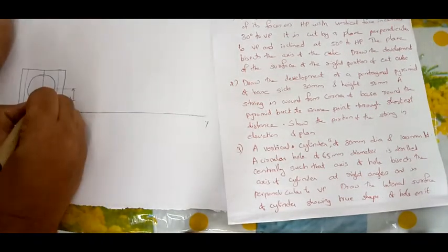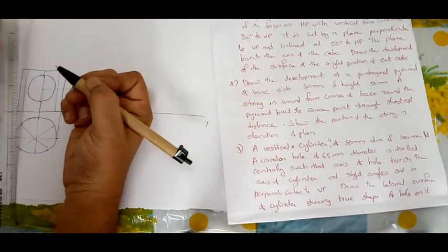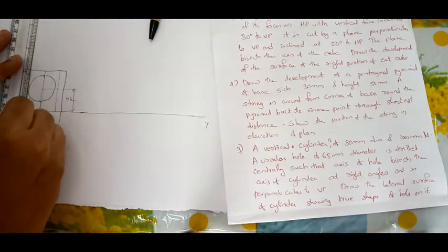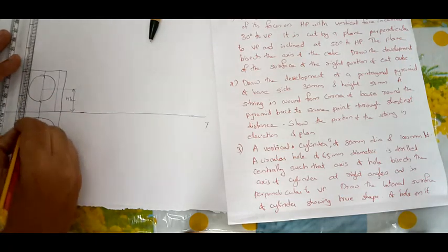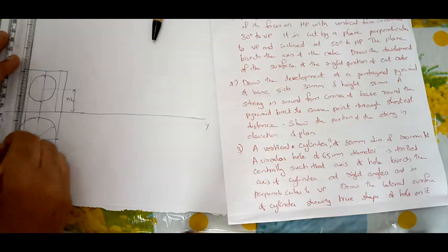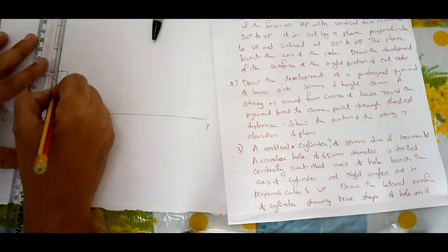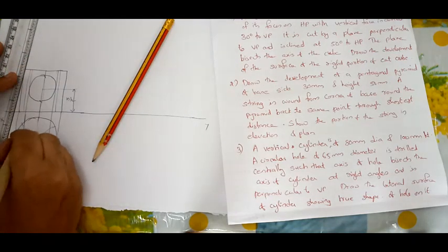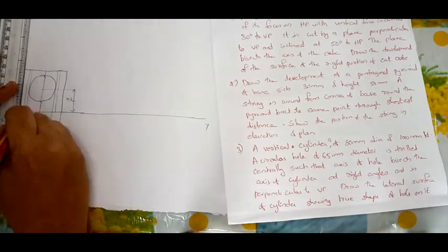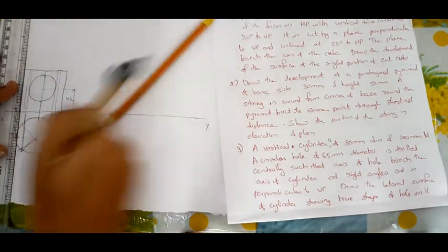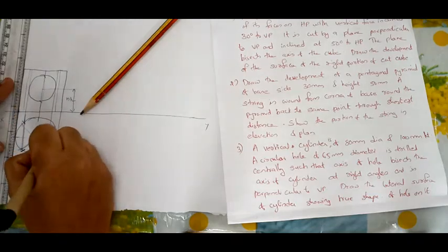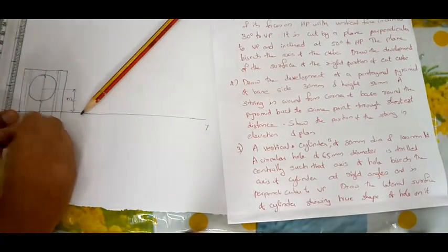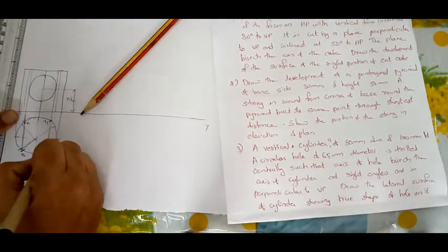So marking the point means here it will be 1 point, here you will get 1 point. Now you have to draw the generator, right extreme. So right extreme generator you have to draw like this and find the corresponding points, top and bottom. Similarly left extreme also you have to draw and find the corresponding points. So it will be cutting here, and let it be cutting here inside, 1, 2, 3, 4. So this you have to find. This way I am naming it as x1, x2, x3, x4.